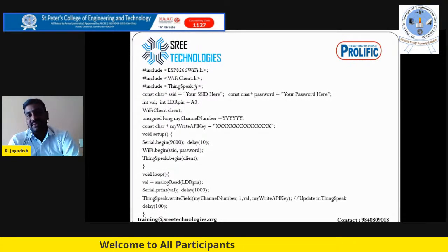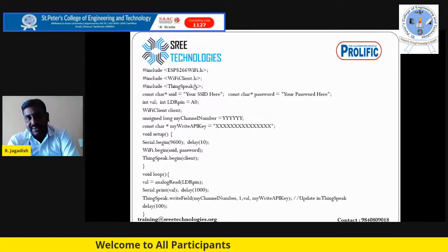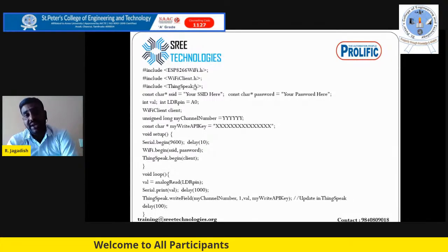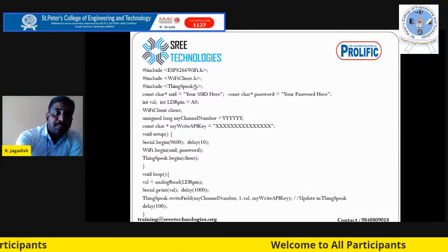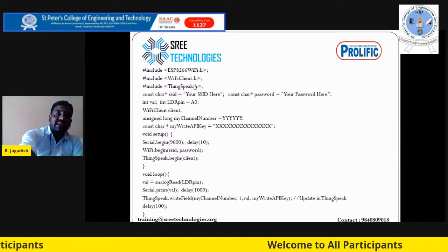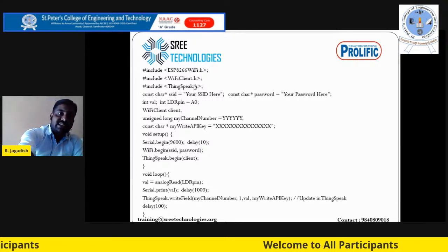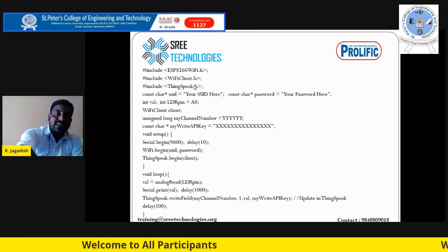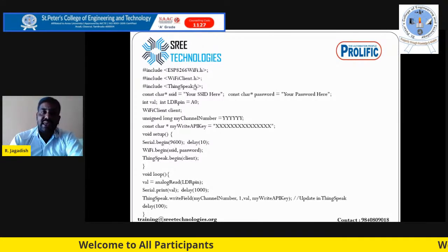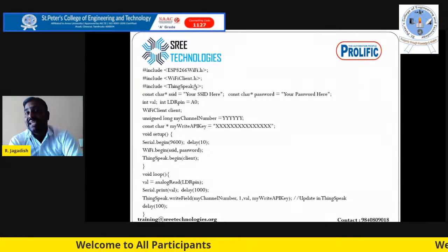Same thing. If you are using the Blynk app, we see the values on the phone. If you are using the ThingSpeak website, go to thingspeak.com, sign up and sign in, and they will provide my channel number and my write API key. The same SSID and password are used, which are the hotspot username and password. So that is the ESP8266 Wi-Fi, the Wi-Fi client and ThingSpeak. We use the ThingSpeak website username and password, the channel number and the API key. This is also standalone code. We do not change anything here.